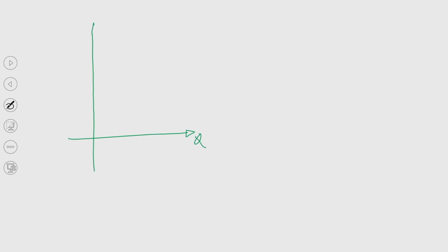So, this is H, this is Q. If we try to draw a particular curve, this is the H-Q curve. When we talk about the H-Q characteristic curve, this is obtained at a constant speed. So this curve always refers to a constant speed, say n1.